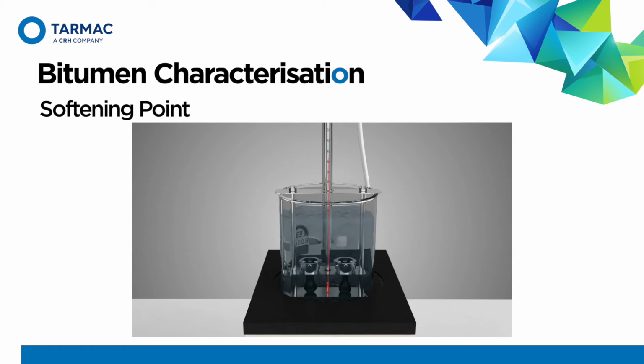Basically, two horizontal discs of bitumen cast in shouldered brass rings are heated at a controlled rate in a liquid bath, while each supports a steel ball. The softening point is reported as the mean of the temperatures at which the two discs soften enough to allow each ball, enveloped in bitumen, to fall a distance of 25 millimeters. So the test is an indicator of the tendency of the material to flow at the elevated temperatures encountered in service.